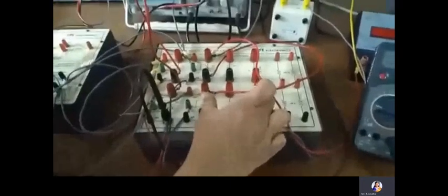Let's look at the connections of fully controlled rectifier. There is not much difference in the connections of half controlled rectifier and fully controlled rectifier. In the half controlled rectifier, D1 and D2 were connected on the lower side. Now instead of 2 diodes, we are going with 4 thyristors. In half controlled rectifier, we had 2 thyristors and 2 diodes. In fully controlled rectifier, we will have all 4 thyristors. The connections remain the same.